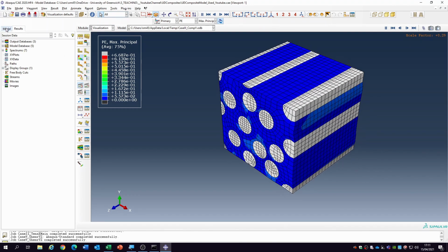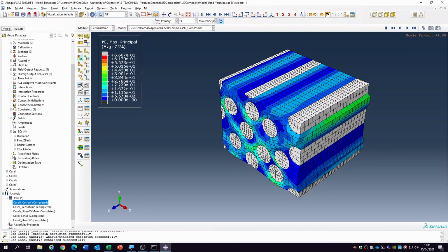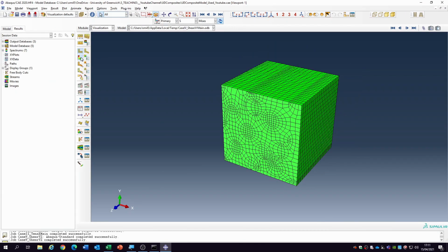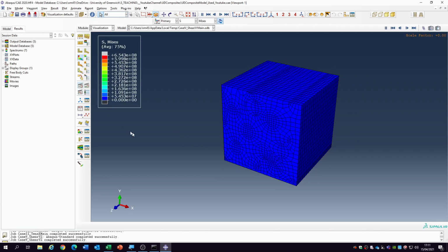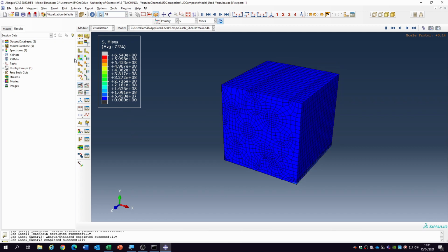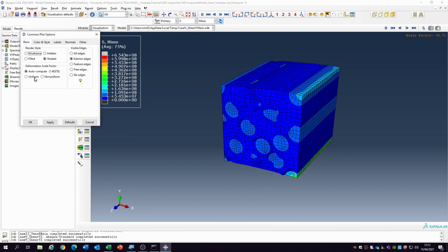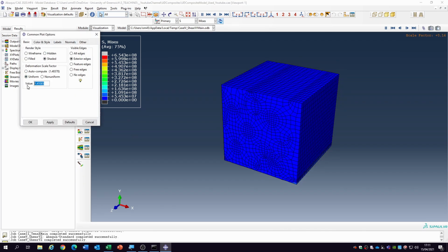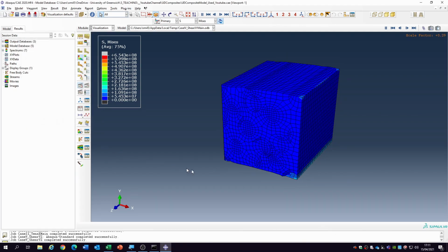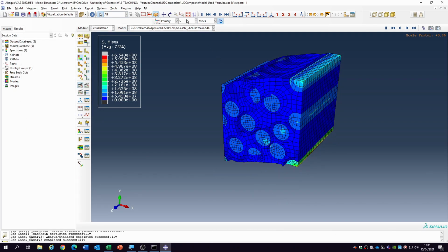Okay, and what about the shear cases? So there's case one, which is the in-plane shear. What would the in-plane shear look like? Okay, so you end up with a behavior where you're shearing on that face and moving that up. It may be a good idea to exaggerate this shear slightly. So instead of 1.5, can we double that to about 3? Then it gives you a better estimate of what's happened.